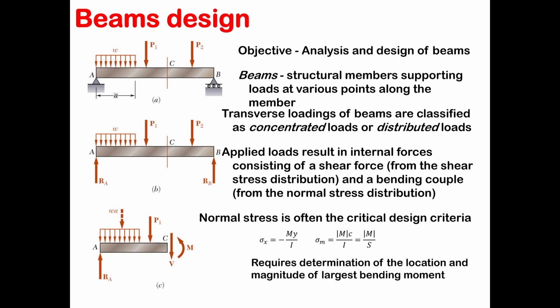And we can always find the normal stress, the maximum stress, which is usually the critical design criteria, using the bending moment formulas we have already seen. But the only problem here is that we have to be able to determine the location and magnitude of the largest bending moments.